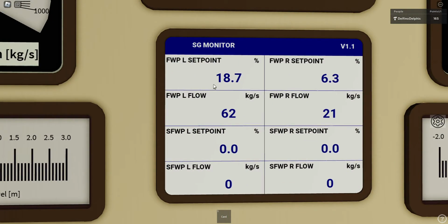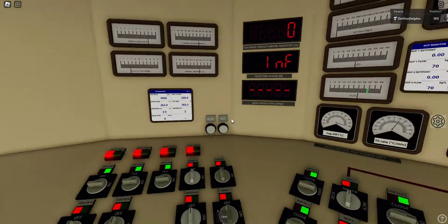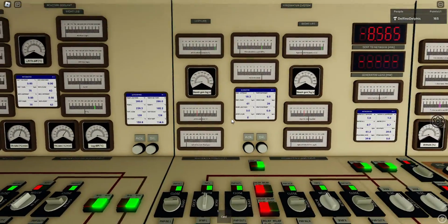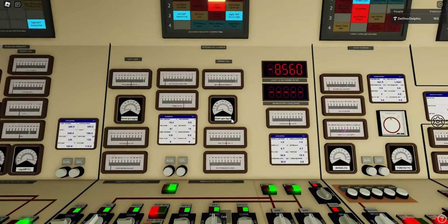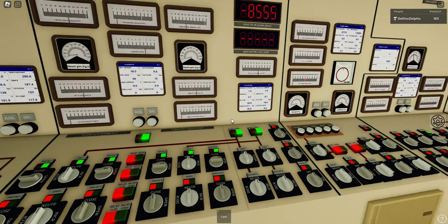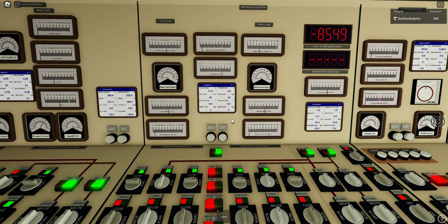You can see the auto control is setting up the set points here. The left one needs more water feed because, as I mentioned, the heater works mainly in the left part, so there is more boiling here. Actually, this one is not boiling any water at this moment. Later on this will average out. This will balance.